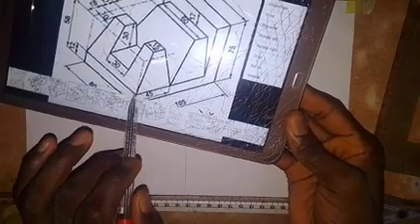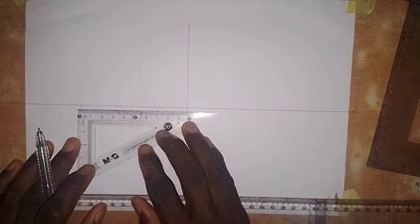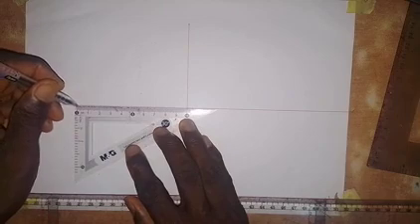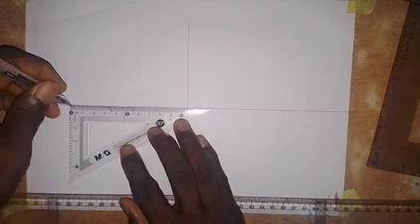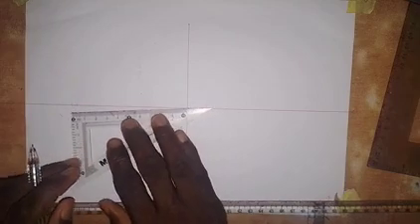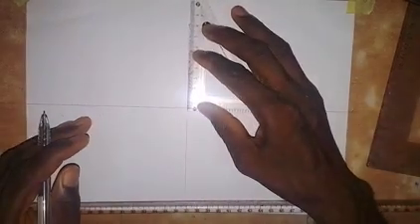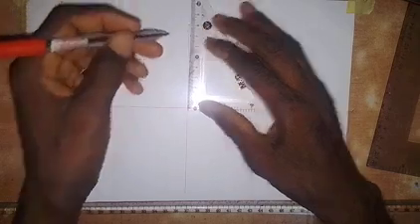I'll be taking dimension from this end here, from this end to this side. So that is how I'm going to take dimension, and it goes like this. Okay, so the first thing I'm going to do is to take a measurement of 105 millimeters. So I'm making use of this set square to take dimension. This is 100 millimeters. Then I will take 5 millimeters in addition to that. So this is 5 millimeters here. So I will now go in this way. So that's the total length. So I will take the height. The height is 75 millimeters of that L shape that we want to produce.